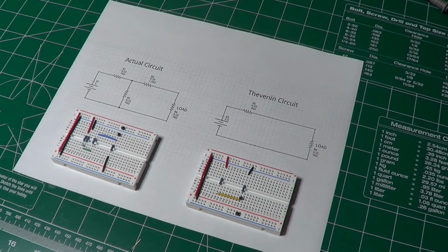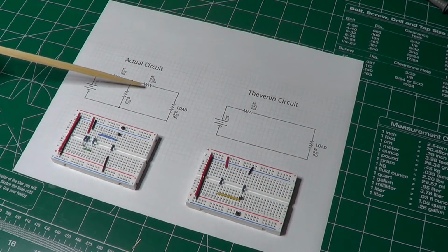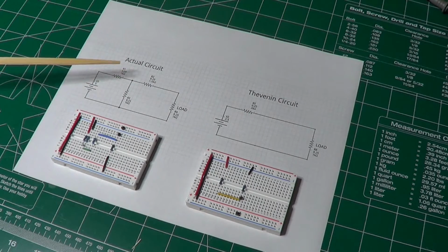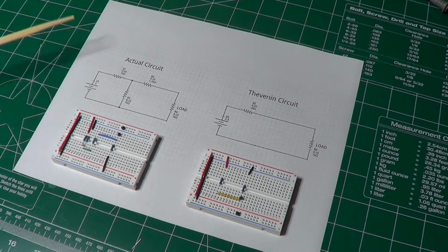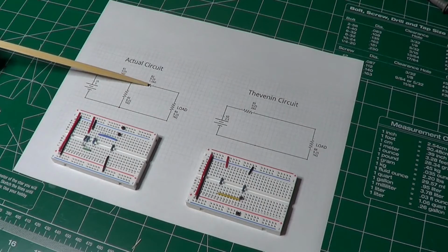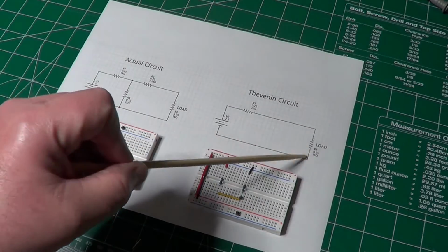And this is easily seen because for the voltage, if we remove the load, there is no current flowing through here, so this is just a voltage divider. The two resistors are the same, and so this point here is half the value of this. This is 5 volts, so this is 2.5. The equivalent resistor means this is shorted, and so these two resistors are in parallel. 1K each becomes 0.5K. In series with 1.5K makes 2K, and there it is. And the load is the same, 1K and 1K.